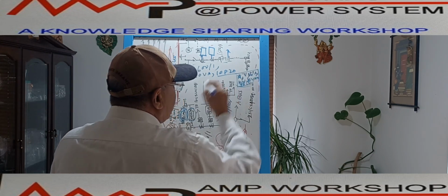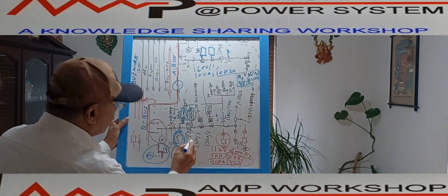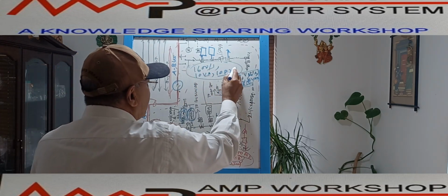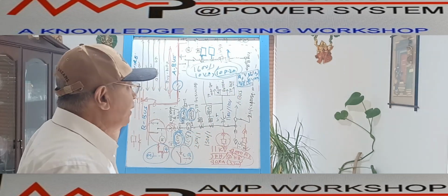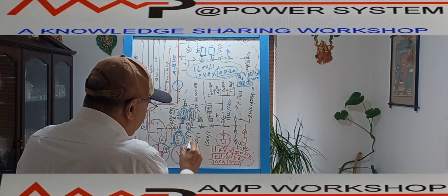Suppose all these things we are metering. So this block will write down all these things. Then on this side we will also write down this ratio, VA. Then the protection class for the CT, maybe for the metering CT the protection class is different, so that also has to be written over here. In this way, all this detail will come over here.